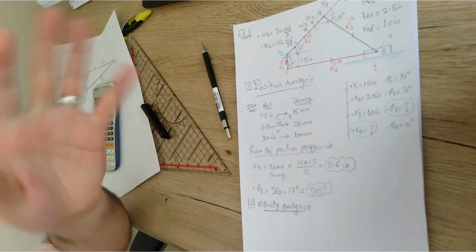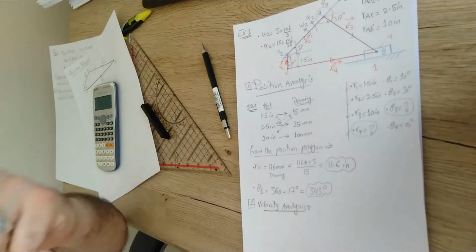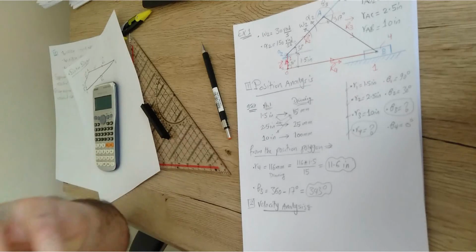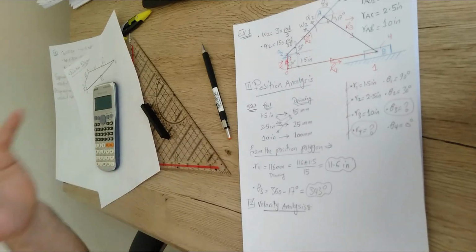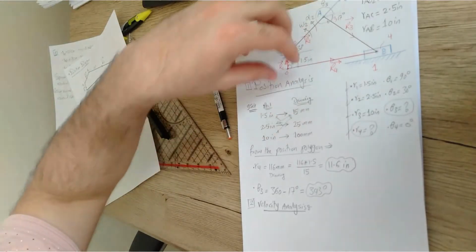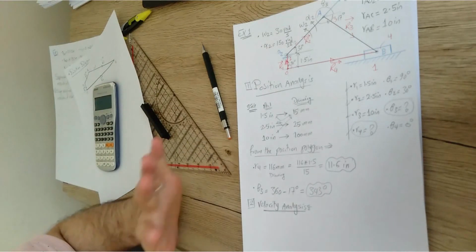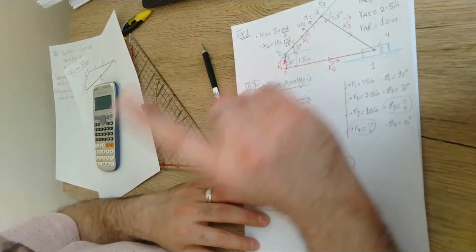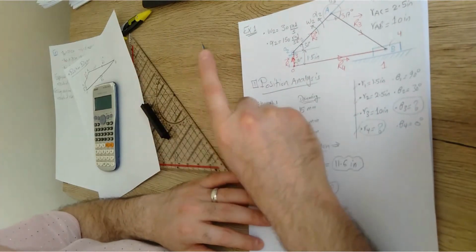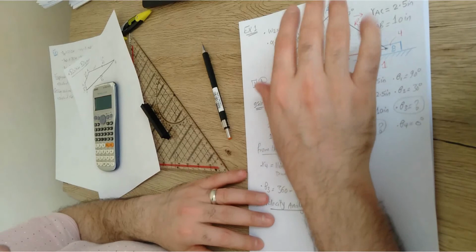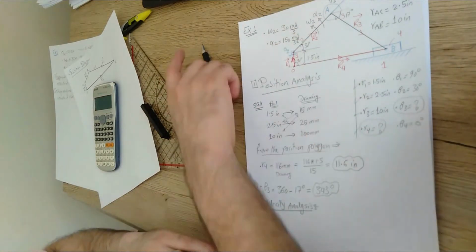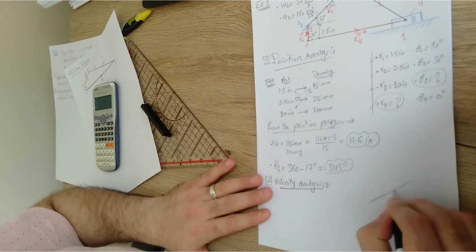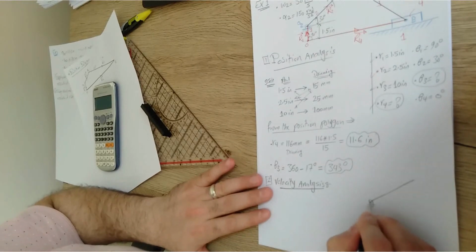Your objective is just to write, forget about the drawing for now, an equation for each one, or put a plan. This equation is gonna be like a plan of how you're gonna draw the velocity line for all of these elements within the velocity polygon. Make sense? So we're gonna work over all of these 3 elements, but starting from the element that has the given information, which is link 2. So I'm gonna start with link 2, and link 2 is generally a link that does rotation about a fixed point, which is point O2.